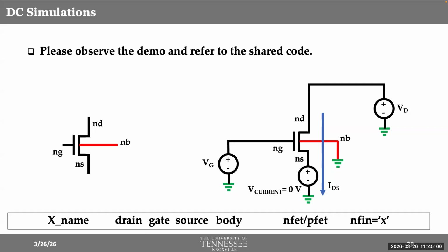Can anybody answer, how can I understand the node sequence looking at a Verilog file? Do you remember in the Verilog file, there is a node list that we have to provide? After you give the module name, then you have to give a list of A, B, C. These are the external nodes. That sequence is maintained here. Whatever sequence you use in the Verilog model, you have to maintain the same sequence for the node naming.